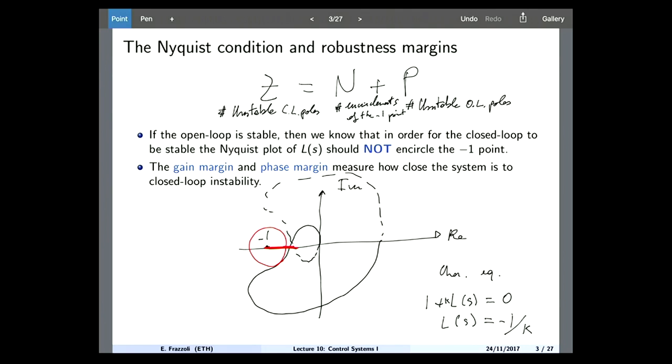Sorry, my scribble here was not exactly precise. Remember that the Nyquist plot must be symmetric, up and down, so the point where these two lines cross must be on the real axis. It was not on the real axis because I'm a little bit sloppy when drawing these things on the iPad. So this is the gain margin shown on the Nyquist plot.